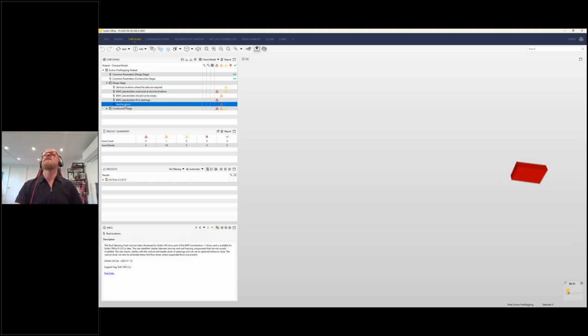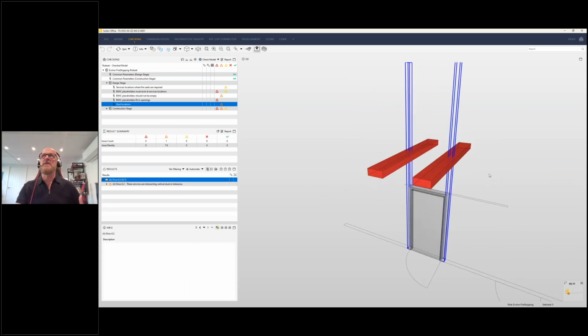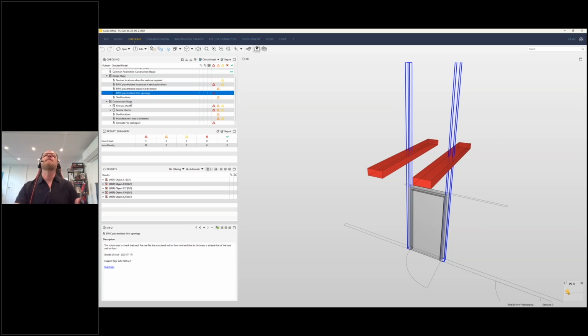And then one other, which is actually a very good result here, is looking at where door positions are and where studs would actually be generated to show whether they pass through potential services information. It doesn't say this is wrong, it's just highlighting where there might be a problem, because obviously other joists can be built here, and alternative arrangements can be made if it's not possible to move the ducts, but it just highlights those positions. So at early stage design, we're doing some simple things to check these things out. And actually, some of these rules aren't even fire stopping rules. Some of them are just generic rules that we've used to help identify where information is needed.